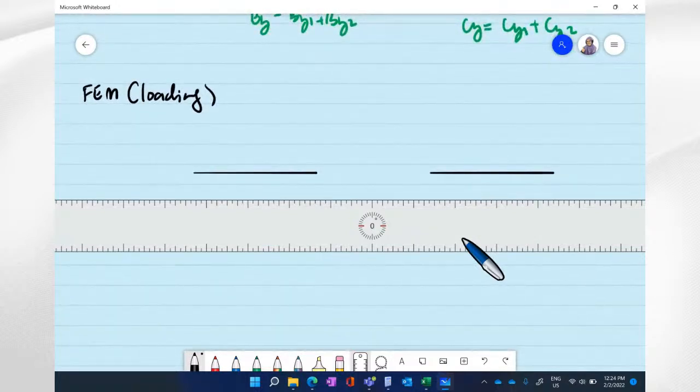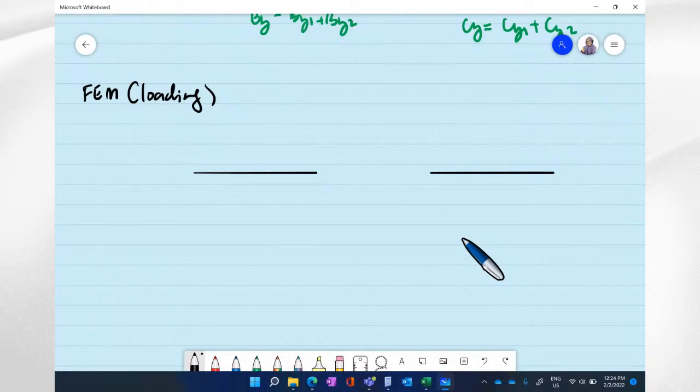The easiest way to do it, I show you now, is by assuming that both ends are fixed. Even though at D it is a pin support, it doesn't matter, we can assume it as fixed. Later on we will find that the total moment in the table is equivalent to 0. This is the assumption that we made when we apply fixed end moment. So this is point load 140, and that is UDL. This is member BC, and this is member CD.